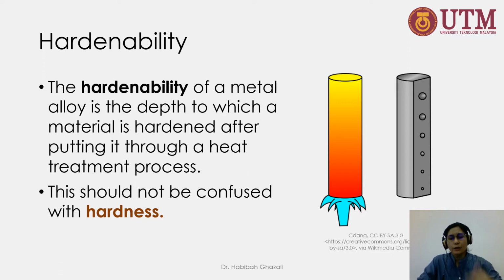In order for material scientists to get these hardenability properties, they conduct what they call the Jominy end-quench test. This is a standard test for measuring the hardenability of steel. It describes the ability of the steel to be hardened in depth by quenching.